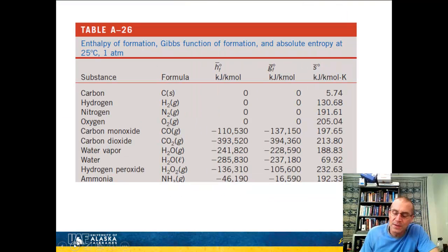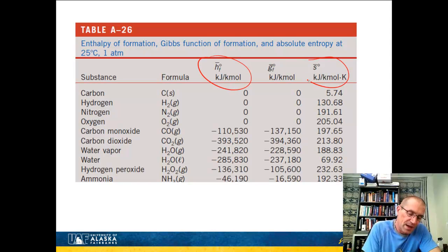Hydrocarbons. Since we don't have tables of ideal gases, you can get that from A26, which was where our enthalpies of formation were. Here's your standard state entropy again. So remember, standard state here means I'm at 1 atmospheric pressure. This whole table is at 25, so you only have it at 1 temperature for various hydrocarbons. I've cut the table off with more hydrocarbons as I go down.